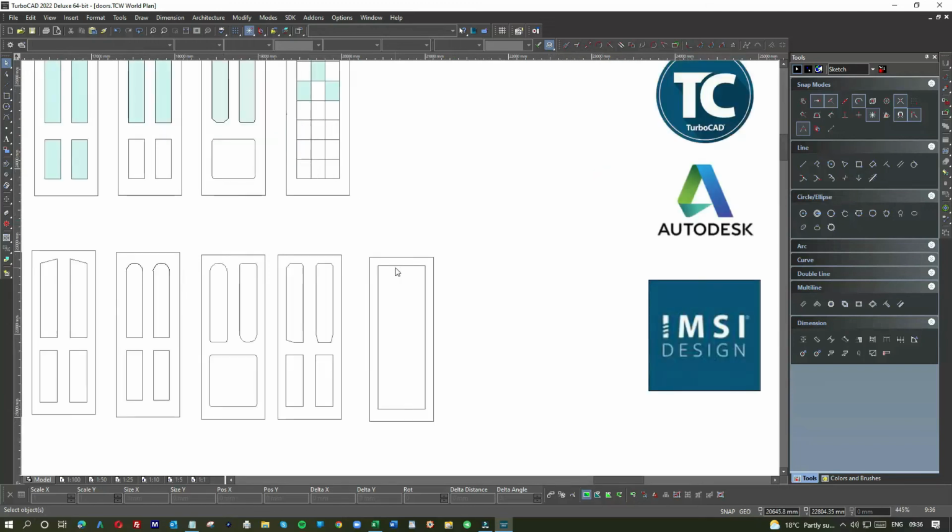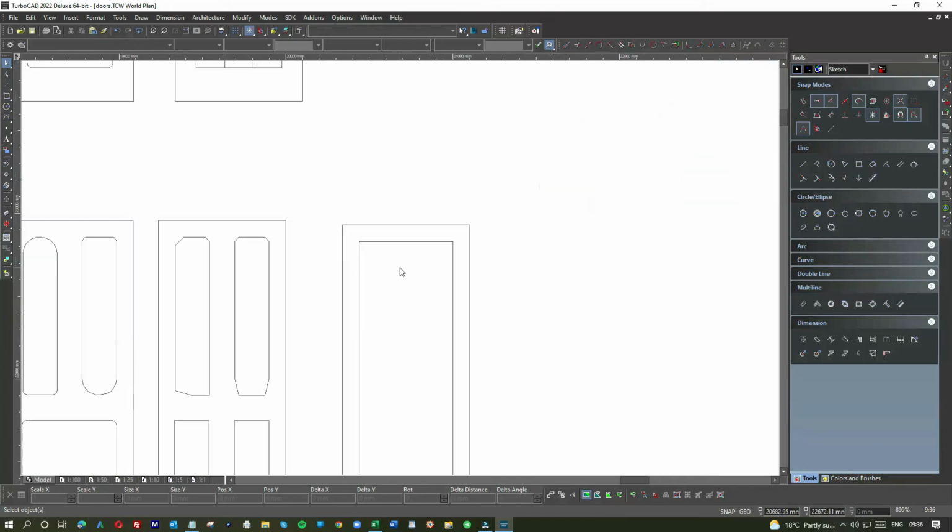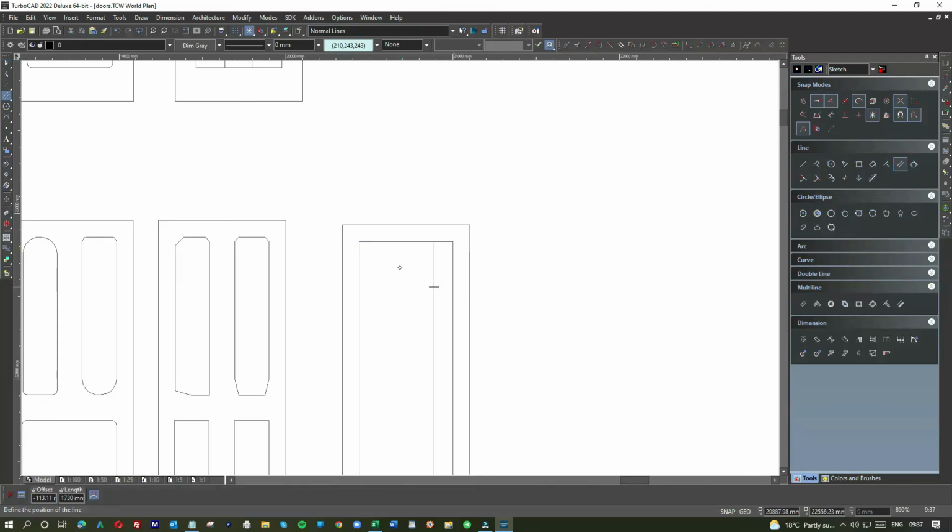Generally it's pattern 21, which means it's three rows across and 7 rows up. What I tend to do, just for speed, is look at the measurement there, which is 562. 2 divided by 3 is 187. So I just go ahead and do it this way. Tab, minus 187.